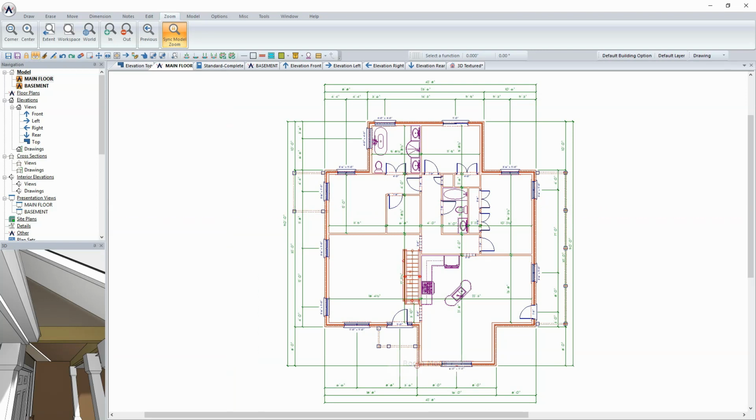Room Mode. SoftPlan's Room Mode adds a host of building materials with a single click of the mouse. Room Mode creates complete interiors by adding wall coverings, crown molding, chair rails, flooring, and ceilings instantaneously. This will not only update the 3D model, but also the bill of materials, allowing for accuracy when estimating the project. Rooms can be added in either 3D or the floor plan. To begin, select Room Mode from the Mode bar.